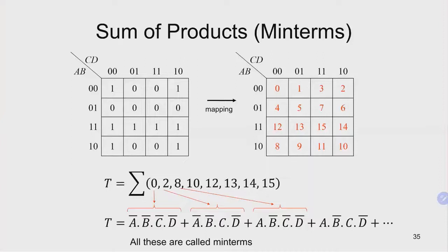So in four variables, the Karnaugh map. So I've put down the index of the Karnaugh map. Meaning that if we take A, B, C, D as a binary number. So for example, this location here will be 0, 0, 1, 0.